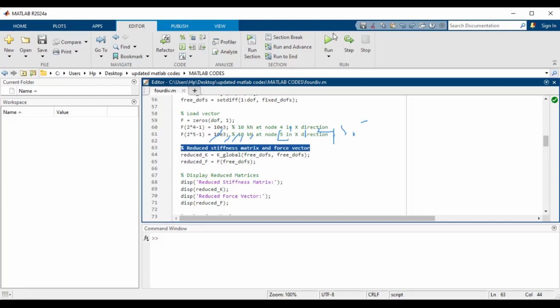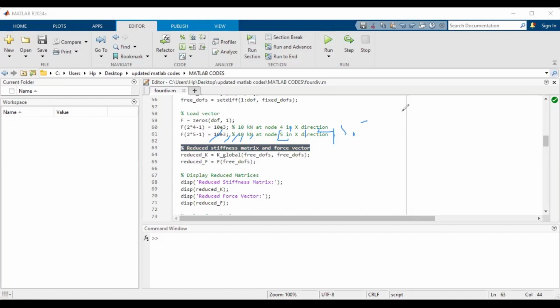So basically, what this reduced is doing is, from the normal FEA analysis, when you have a boundary condition, depending on what the boundary condition is, it has a way of deciding what happens to your global stiffness. So when you're saying this one is fixed, that means the nodes associated with this fixed part are going to be 0. And when they are 0, the whole matrix is going to reduce eventually, isn't it?